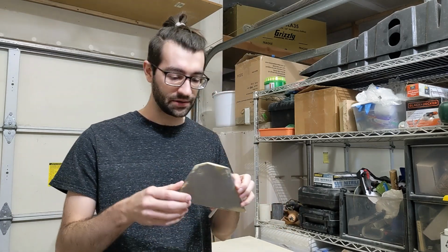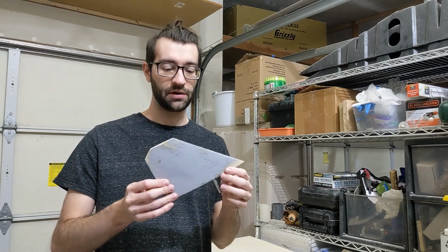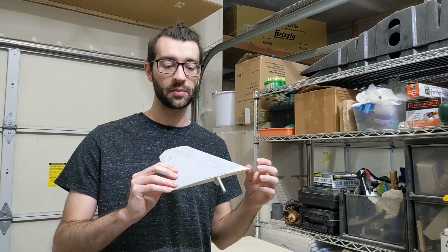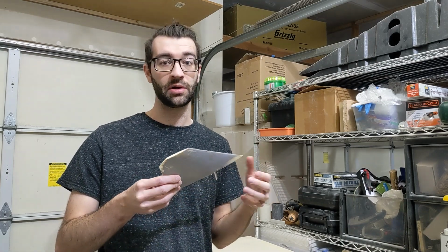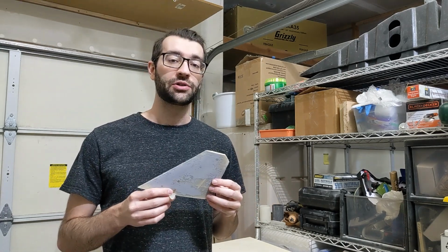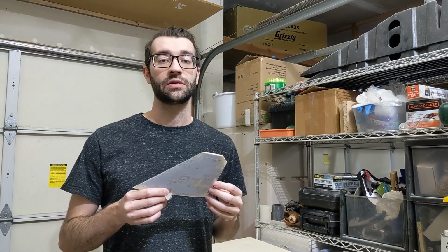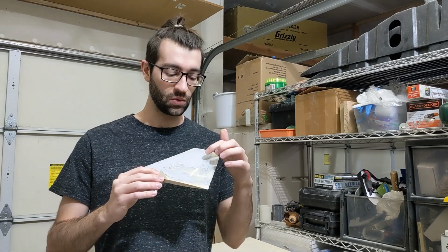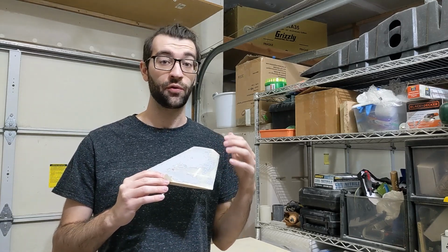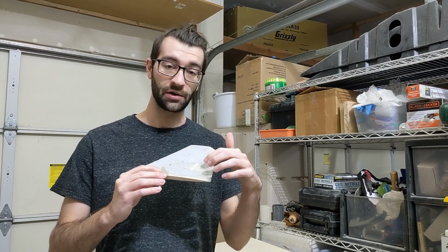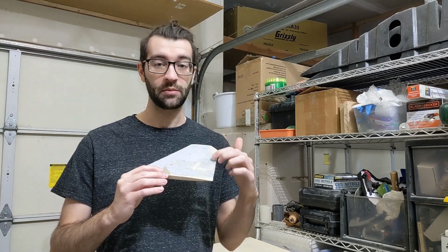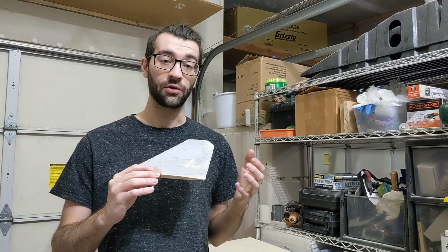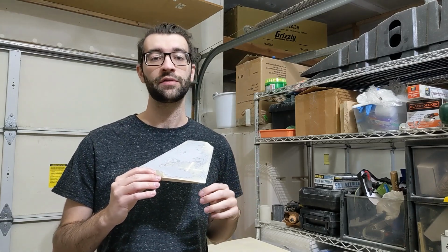For the horizontal stabilizer, I think a contributor to it being heavier is the fact that all the primer stuck to the skins after it released from the molds. So I think that's adding a little bit of weight too. But going forward, I'll make sure to weigh each part as I build it and make sure it's not too much heavier than the estimate. What I'll do for the next subcomponent as I build it is weigh all of the individual parts separately before I glue it all together. For example, I'll weigh all the balsa parts separately, I'll weigh the fiberglass skins separately, and I'll weigh the birch plywood parts separately. That way I'll really be able to pinpoint where the extra weight is coming from.